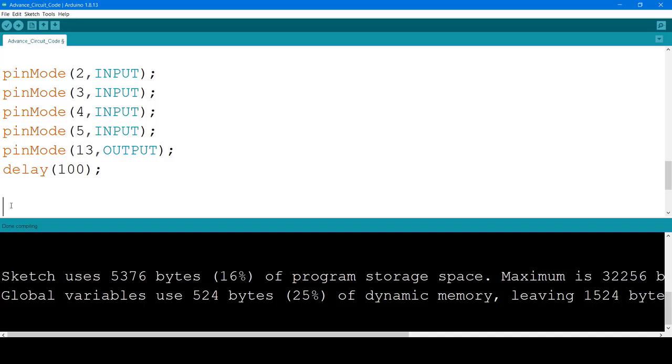Now, to read this data, we need to initialize a variable. Let's call it value button, and let's use the EEPROM.read function, and it will take the address as input. Now the address is basically the EEPROM address, and the value button is basically a variable that will store the current button that was pressed or the previously pressed button in case of power loss.